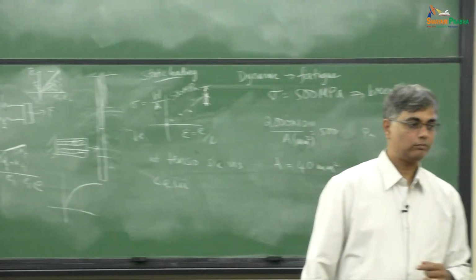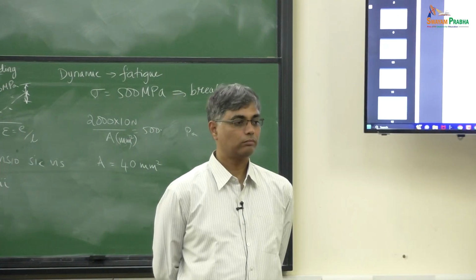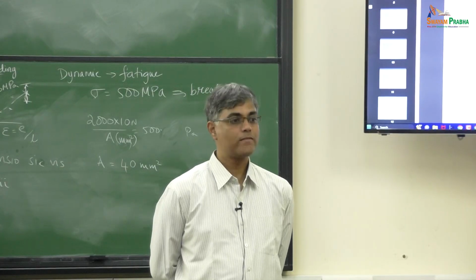Yes. Sir, yes, sir. So let's take the 2 springs. To get the extension to be E1, the force must be E1 into K1 plus K2. That is E1 into K1 plus E1 into K2. After that, the first spring breaks. So now only K2 is there and it is E1 into K2.